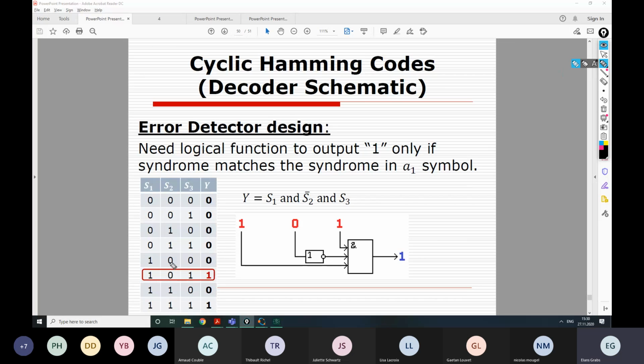And I think perhaps I have slightly misplaced these two values, right? And sorry, it's actually not a table of the syndromes. It's not this table. They are just typed in the possible combinations of these syndrome values. And we need a logical function that would give output 1 only in this case. For any other case, the output should be 0. So it's quite simple to make.